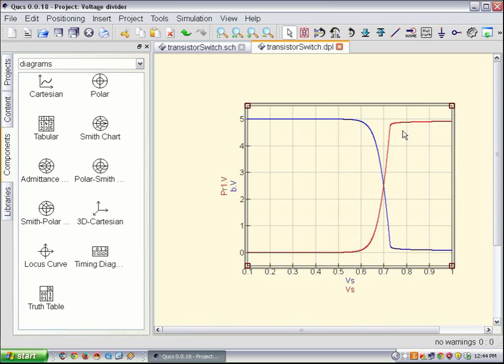So your resistor is switched on while your transistor is switched off. So if I use the output at A, that is in blue, that is B, then I'm using the transistor as a switch. But instead of the resistor, I can have any other circuit like a relay or LED light or anything. Then it will turn on when the voltage crosses.